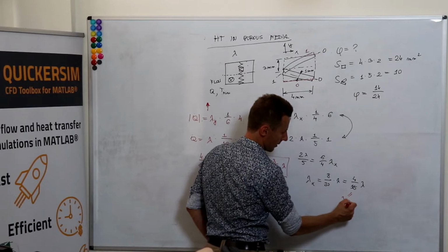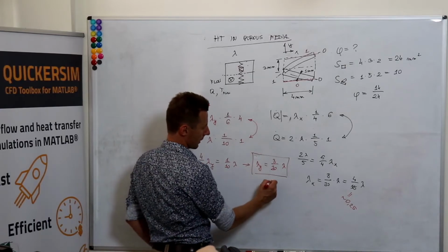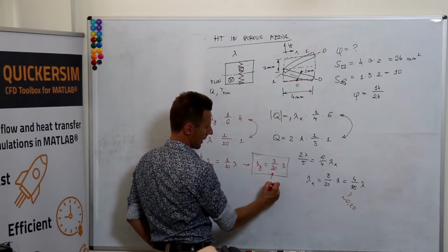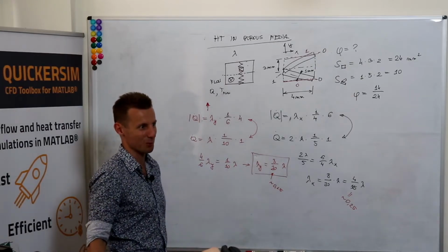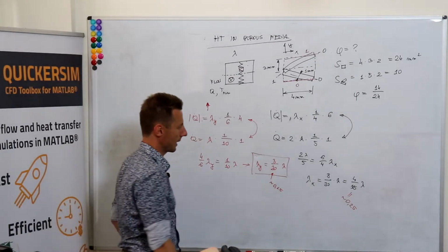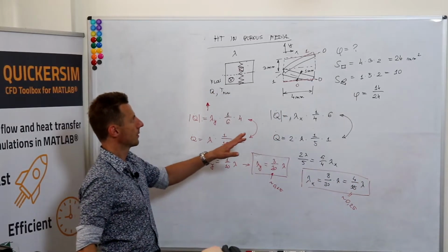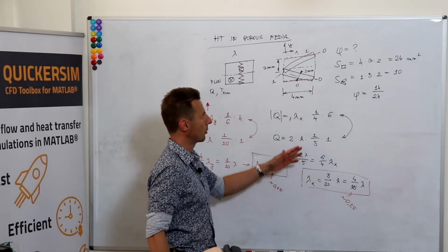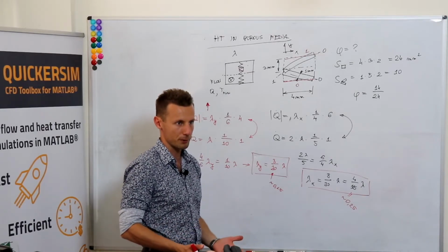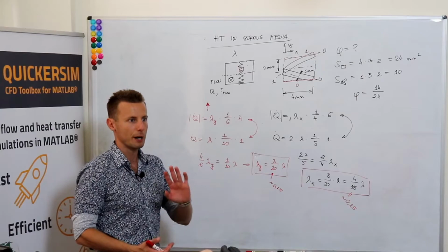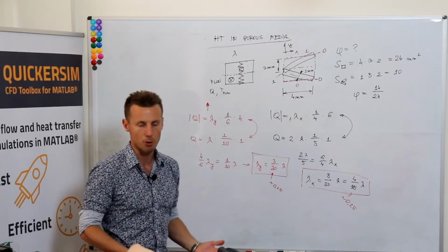And you can clearly see that one is approximately that. But clearly that one is approximately something like that. Well, it's not approximately, it's equal to 1500. So you can clearly see that you need to treat your porous medium and the heat transfer as heat transfer in the orthotropic material if you want to replace really representing the structure of the material by some averaged model of the porous medium.